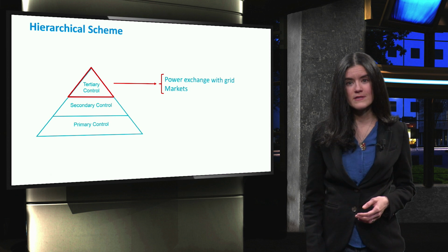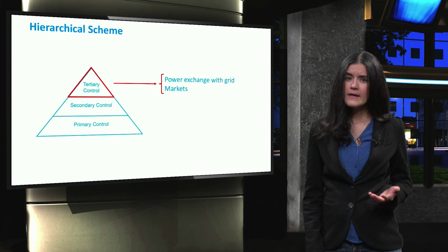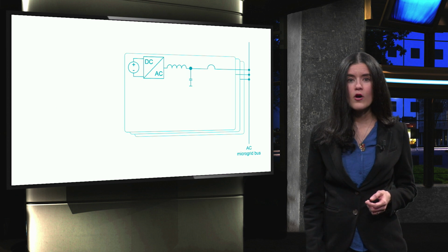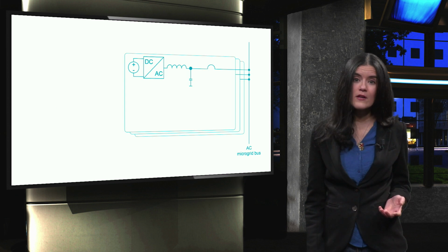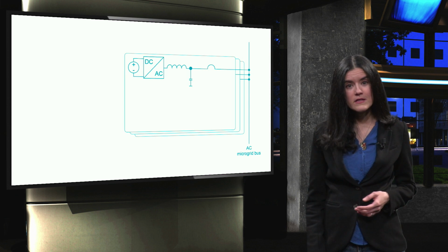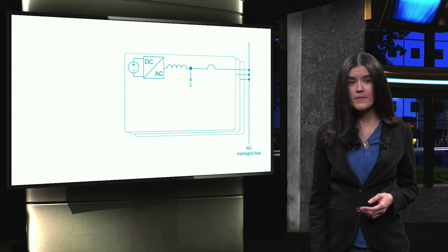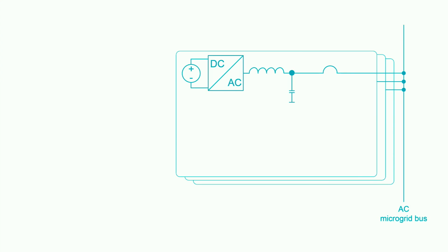and regulatory signals. Here we can see a better example of the implementation of primary, secondary, and tertiary controls in a distributed generation system. Local control acts on power electronics interfaces that connect generators, loads, or batteries to the microgrid bus. The control that acts on the power converter here, a DC to AC inverter, is based on voltage or current.